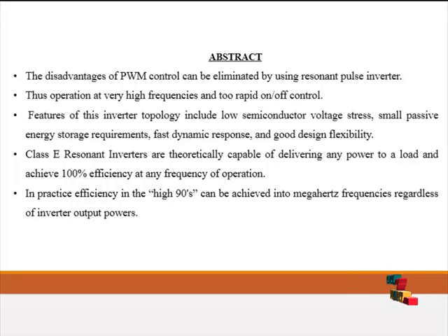These features include low semiconductor voltage stress, small passive energy storage requirements, fast dynamic response, and good design flexibility, and so on. Generally, Class E resonant inverters are theoretically capable of delivering any power to a load and achieving 100% efficiency at any frequency of operation. In practice, efficiency in the high 90s can be achieved into MHz frequencies regardless of inverter output powers.